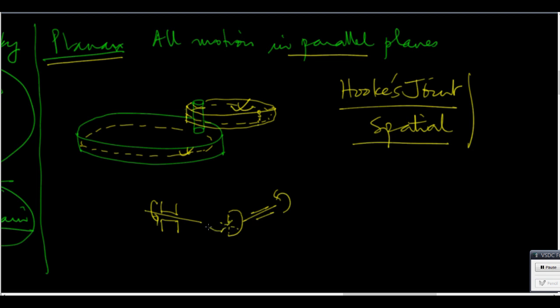And then over here, this semicircle. So this semicircular part is attached to this. This semicircular part is attached to that. And there is a common plus shaped link here, like this. So this one rotates about this one and about those. And this is the Hooke's joint. In the book, in figure 1.7, it is slightly confusing because only quarter circles are shown, but this is the mechanism.